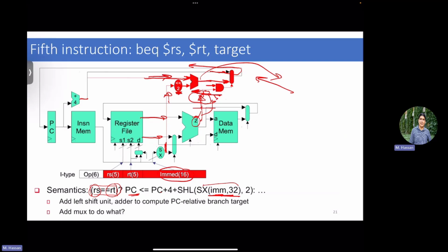Let's start with the simplest one. No branch, no jump, nothing. Program counter plus 4. What path do I take? Well, simply I have program counter plus 4. I go to that line. My selection line, because this is a normal add instruction, for example, is going to be 0. It's not a branch, so I pick that one. And this one here, it's also not a jump, so I continue with this one, and then I load it to the program counter.